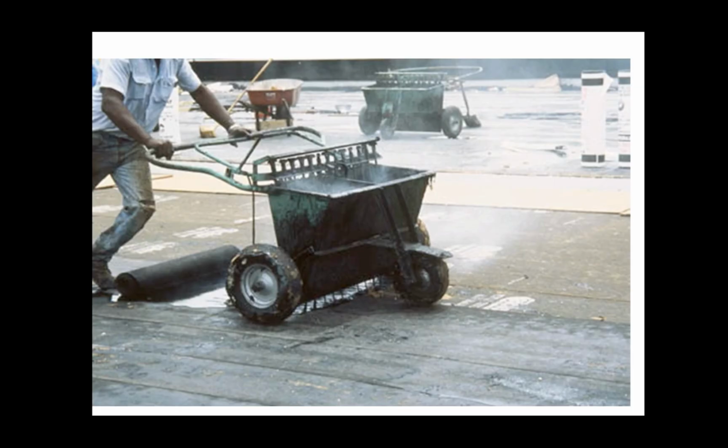And then here you see the application of that tack coat for the next layer of material. Just to warn you, if you ever have to go to a rooftop or a site where this is being performed on one of your buildings, it's kind of stinky sometimes. Don't wear good shoes. It'll stick to your shoes like crazy. It's just like building an asphalt roadway. So it gets hot during application. The material stays hot for a long time. And you have to be aware of all those other potential dangers between the heat and the tackiness and the stickiness.